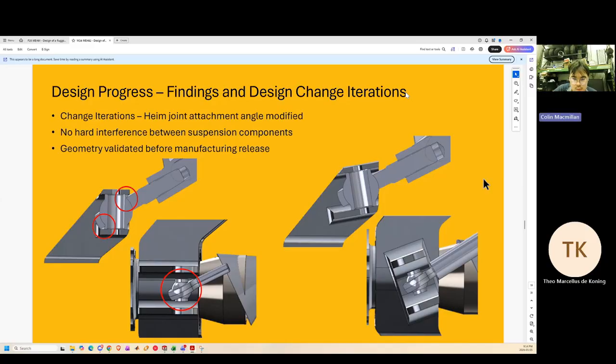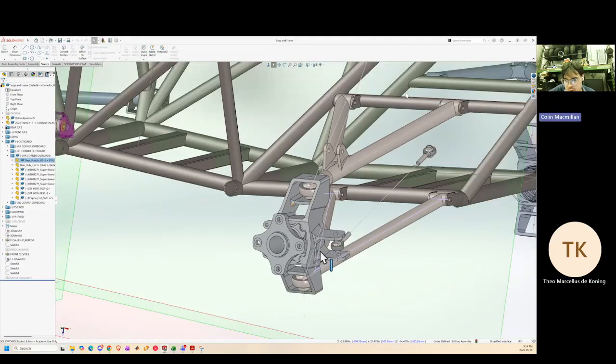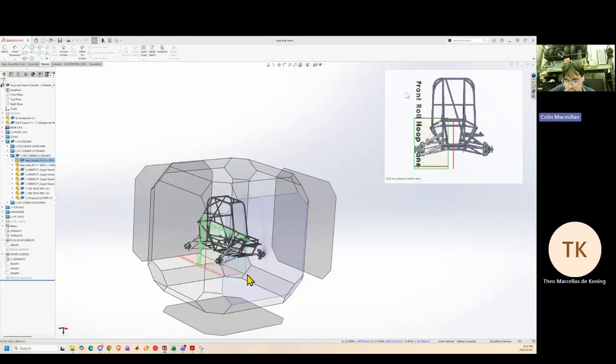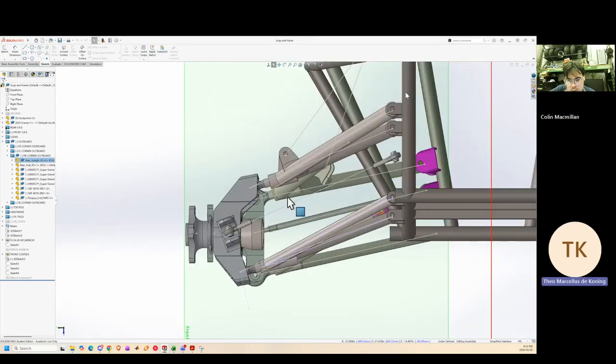Because now the control arms are fundamentally at different angles relative to the upright. So the control arm position is staying the same, and the upright position is also staying the same. Yeah, it's just the geometry of the upright that is different. Okay, got it.